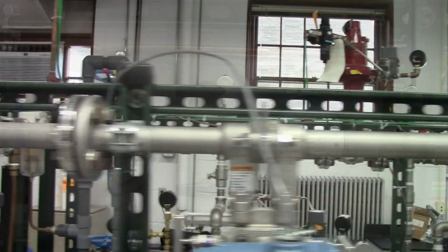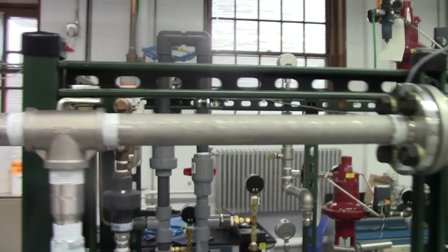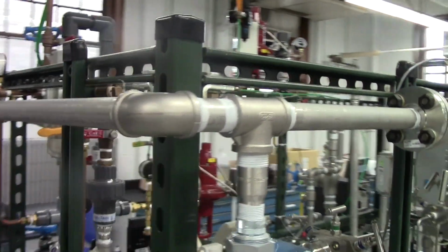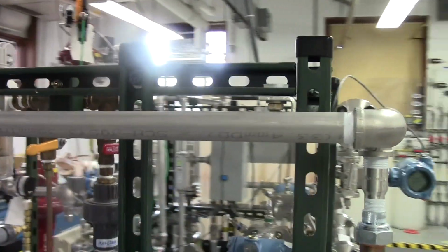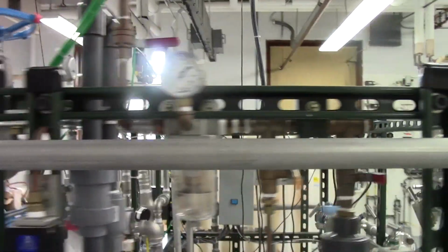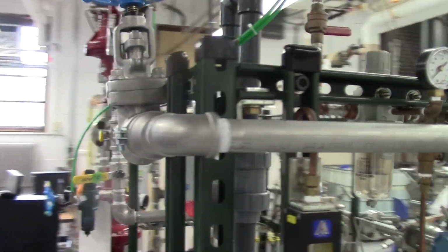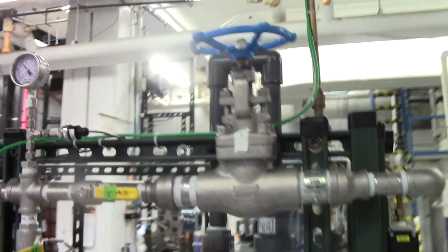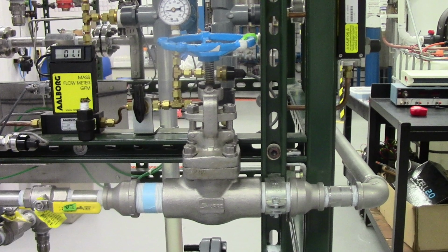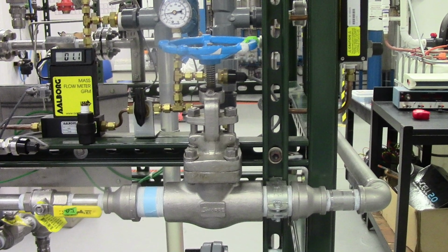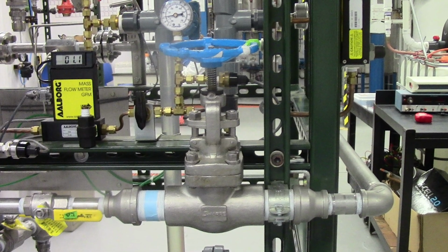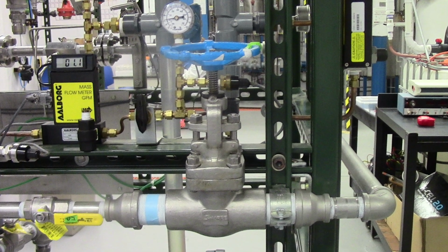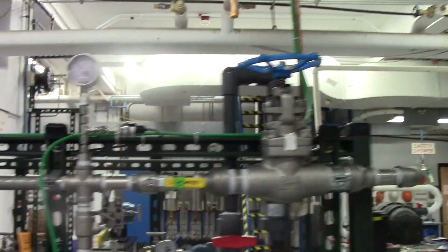After leaving the Venturi meter, the water flows around to the other side of the apparatus and enters the globe valve. Leaving the valve partially open will cause the water to divert its flow to fit into the smaller area. In the same way that a Venturi meter causes friction, so does the globe valve. This causes the water to lose energy, causing the pressure to lower in the pipe after going through the globe valve.